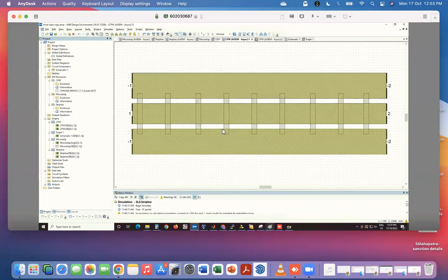One is that your energy will convert from the CPW mode into the slotted line mode, because the excitation in the CPW mode also behaves like a partial excitation of the slot line mode. And then that can convert, and in the slot line mode, there are reflections on either end.